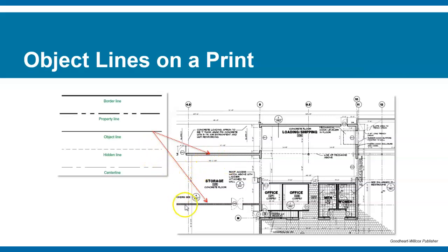While we're here, we might as well make reference to, okay, and here's another object line, you see? So you have another wall, and then you see what looks like these two semicircles. Those semicircles have a light dashed line here and a solid dashed line there. And then here we got this solid straight line here and a solid straight line there that touches each end of the wall. These are doors, and this is a pair of doors, and it's showing you their swinging path. If they were to swing and pivot at that point, they would travel in these little semicircles.